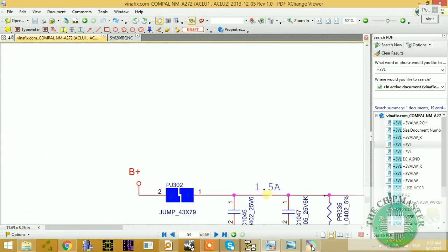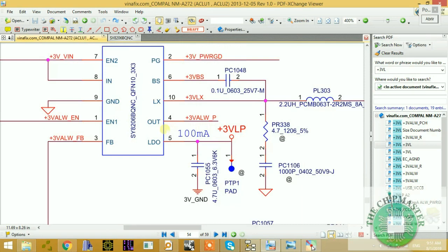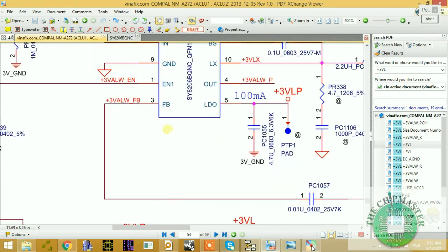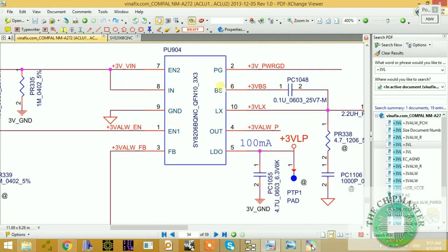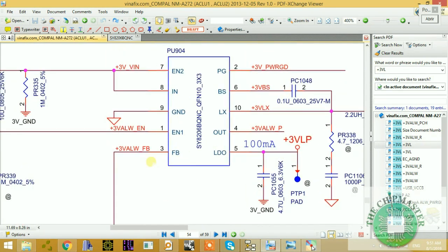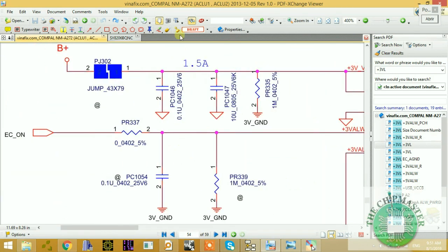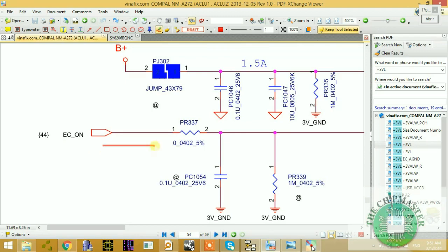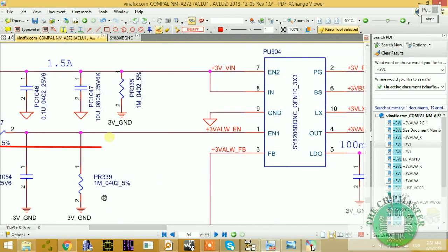Yes. Alright, so the supply is out and it's powering the IO controller. What's the next working condition? Anybody can tell me what's the next working condition of this chip? Now we have supply, we have an LD output. Next we need enable. So the enable is coming from who? This signal. Who is sending this signal? This signal is coming from the IO controller, EC, as I said before, and it's coming to pin number 1. Simple, right? To turn on this chip. So it gets power. Now it is being told to start, and the IO controller gets this signal.